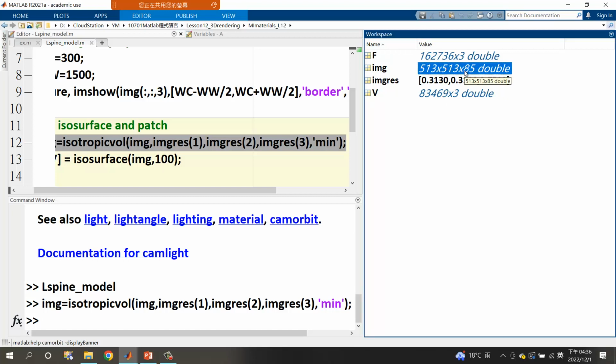I actually increased the number of slices because you need to correct this issue, right? For each slice, it can actually create 10 more slices because the in-plane resolution is more like 0.3, right? But slice thickness is 3.7. So they are 10 times different. So you can see I actually increased the slice count by around 10, I have to say.